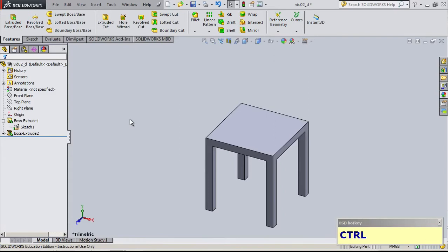So when you are creating complicated objects, try to see if you can actually combine the sketches, which will make your life a little bit easier. You can also try to figure out if you can actually extrude it along the X direction, which I'll leave to your imagination. So essentially you would create one block, and then you would need to do an extrude cut. So this is the extrude cut over here. So just like extrude adds material, you can do extrude cut, which will remove material to create that particular shape.